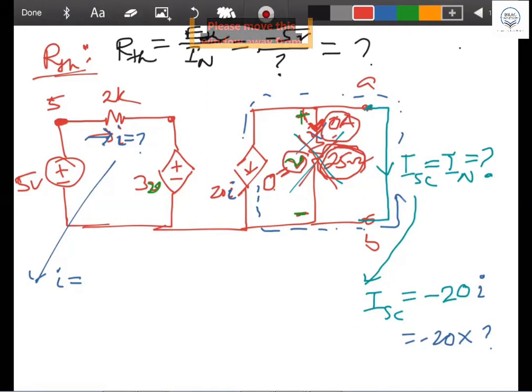Hey, anybody got question? No, sir. Somebody said 20I. How come you said 20I? Because you short circuited. All the 20I go through the short circuit path. No current is flowing through the 20 ohm resistor. So the voltage is 0, isn't it? Hey, you understand it? Yes, sir. If it is 0, then you say 3V. Will it be 3V?